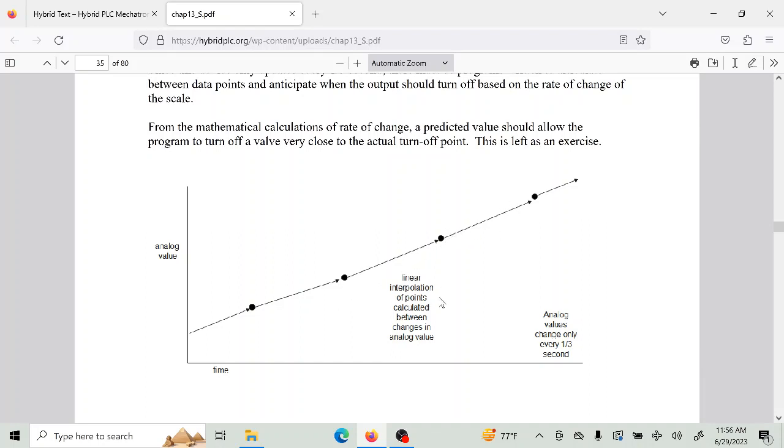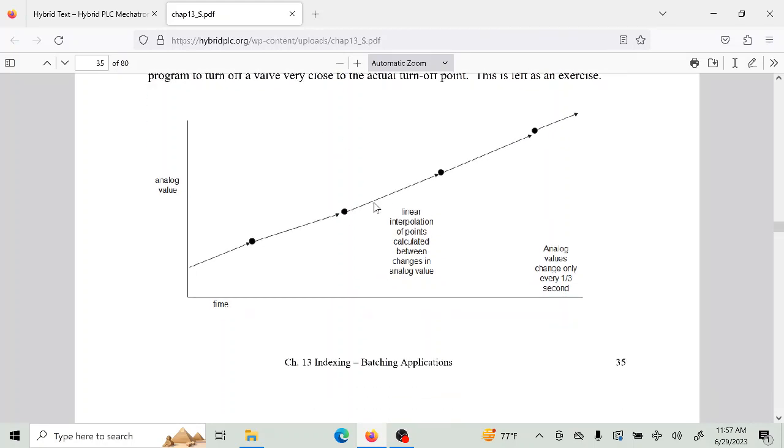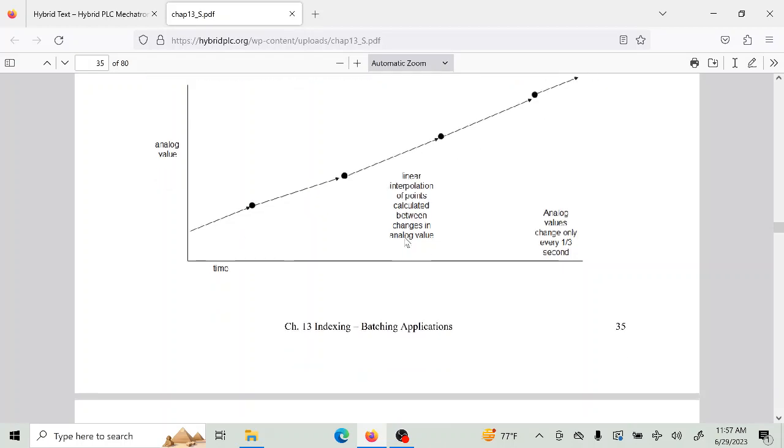So you have to decide as an engineer how best to attack the program. If you want an update every scan, you might want to pick the SIWAREX or the Allen Bradley equivalent. But if you want to cheapen it and you have a lot of systems, you may want to use something like this. But here you're going to have to write this little program that does the linear interpolation. If you want to do that, you can, but it takes time, and time is money. So you have to decide which way you're going to go.